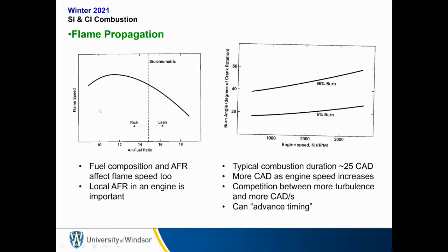So local air-fuel ratio in an engine is important, particularly in a spark ignition. We want to have a very well-mixed charge because we want the flame to propagate at an even speed. We don't want it to speed up and slow down as it goes through pockets of different air-fuel ratios.